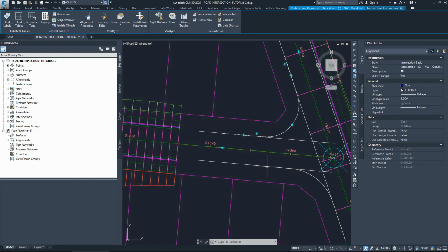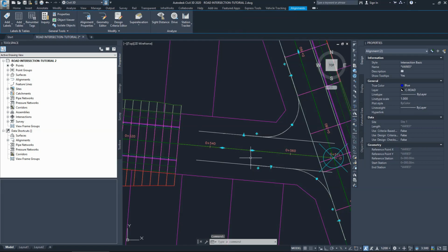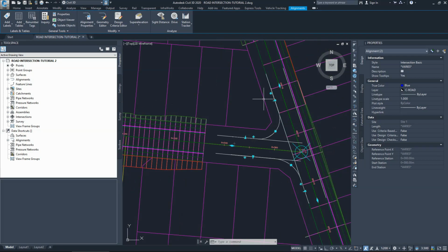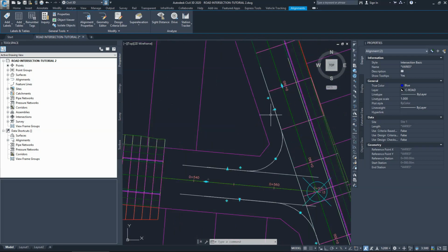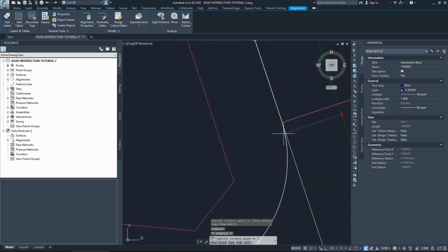So if I make sure the two grids are aligned together, that will make sure that when I create the corridors, both corridors finish at the same line. So what we can do is just slide this grid back to that grid. In that way, both corridors will finish at the same point. That will save us time at the end to align the corridors together. This point here is not very important. We can just slide it, if you want, back to the intersection as we agreed.